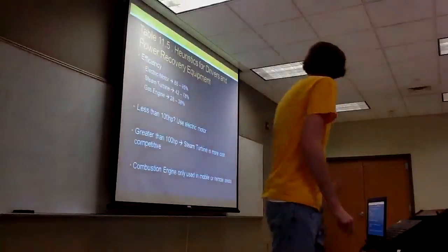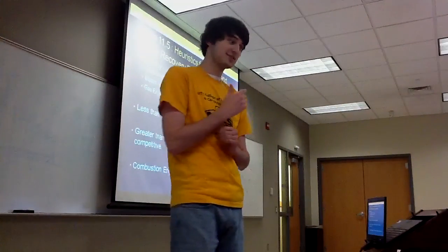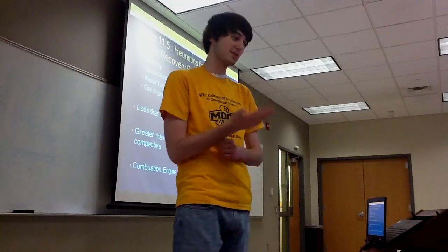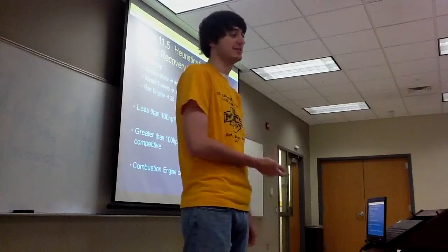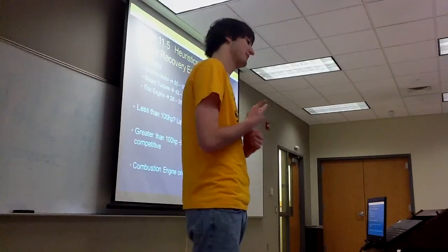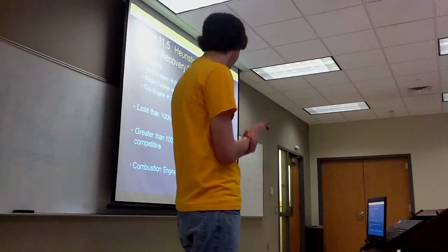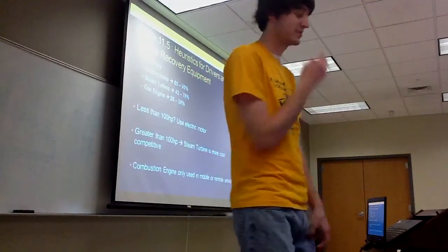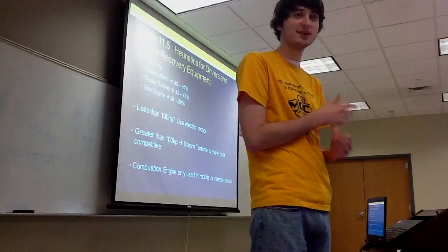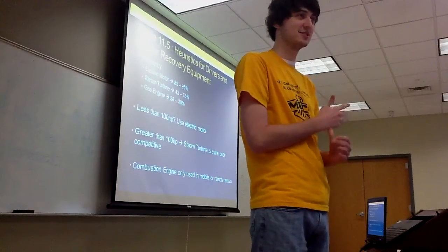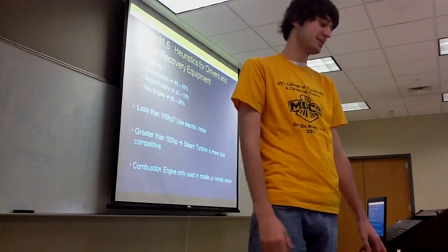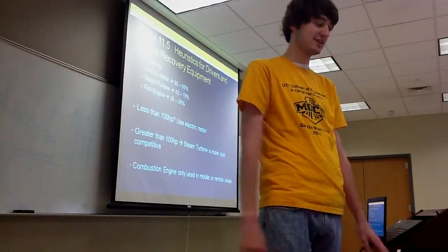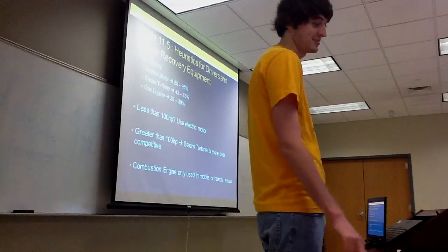So here is an example. This is one of the smaller of the tables in the book. This is for drivers and power recovery equipment, and they just say, here's basic efficiencies for different motors, and so an electric motor runs at about 85 to 95% efficiency. That's just an approximation. A steam turbine's 42 to 78, and then a gas engine's 28 to 38% efficient.